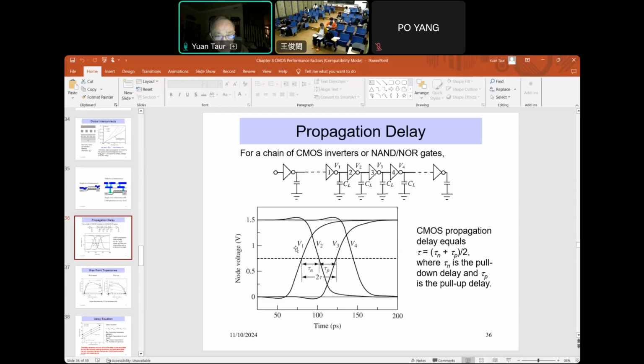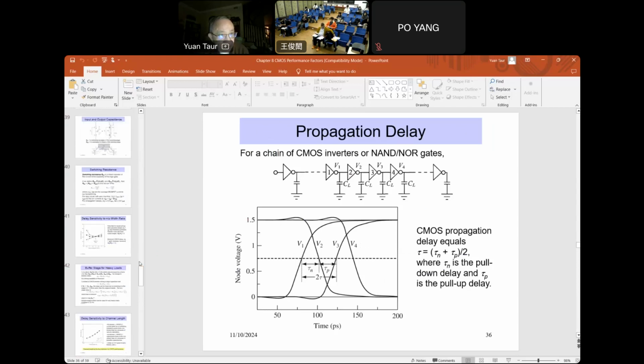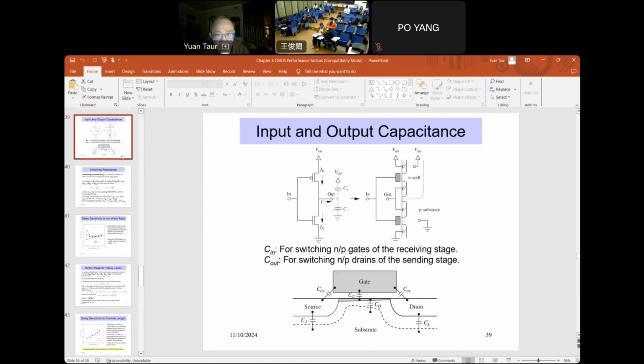And that's because of a capacitive coupling. Okay, so when the gate goes up, the first effect on the drain, without discharging, is that the drain will go up, will follow the gate because of a capacitive coupling.